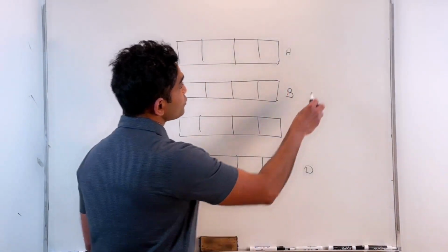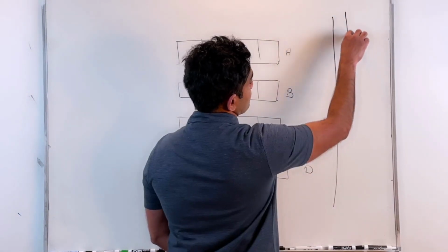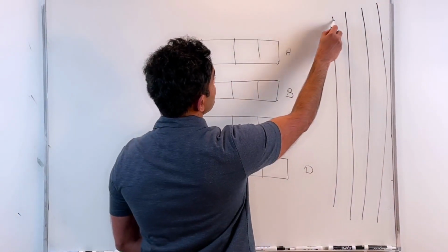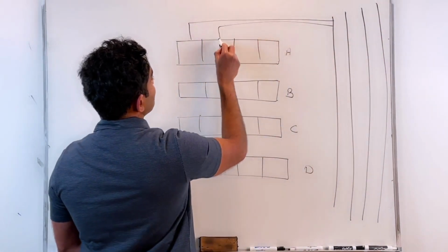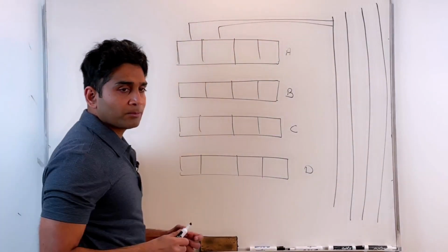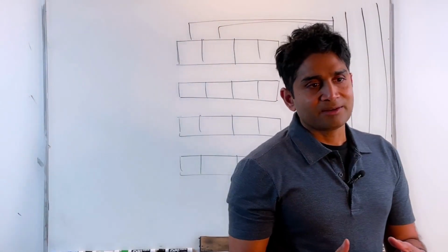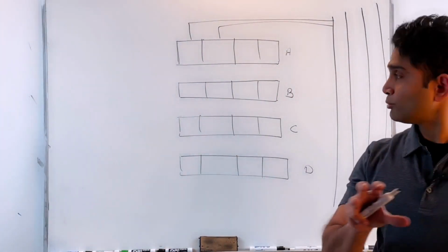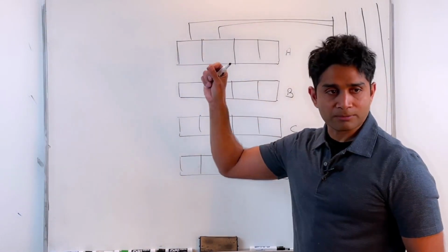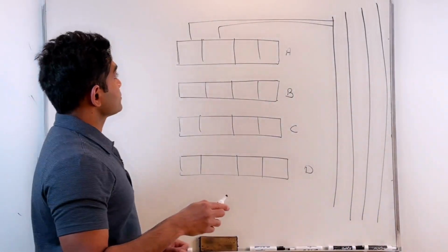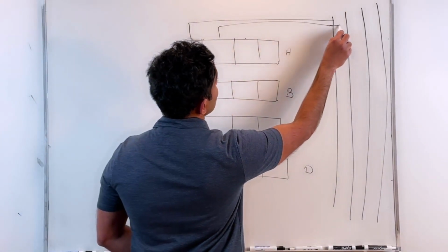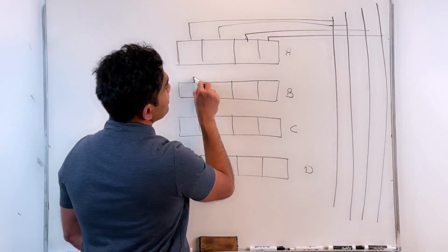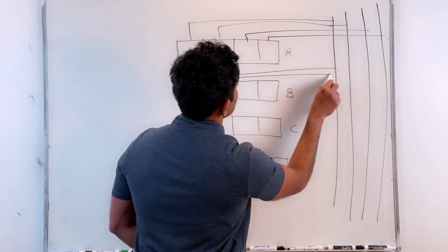And again, I have this common data bus, right? 4 lines that are connected to each of my registers, something like this. Again, when I show this, that means you need to assume that we have this entire module of having the multiplexer and the D flip-flop together within each of these blocks. Okay, so that's my registers. That goes here, that goes there, that goes here. Likewise, each of my registers is connected to the data bus.